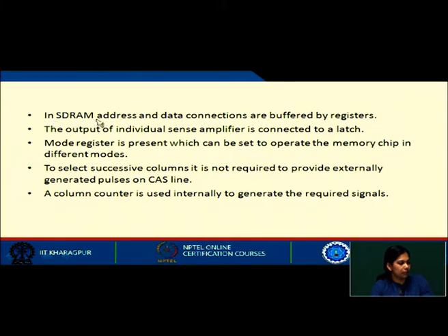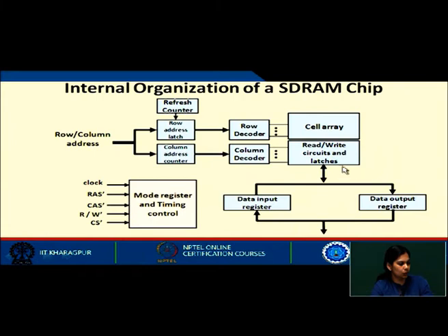In SDRAM, the address and data connections are buffered by registers. The output of each individual sense amplifier is connected to a latch.